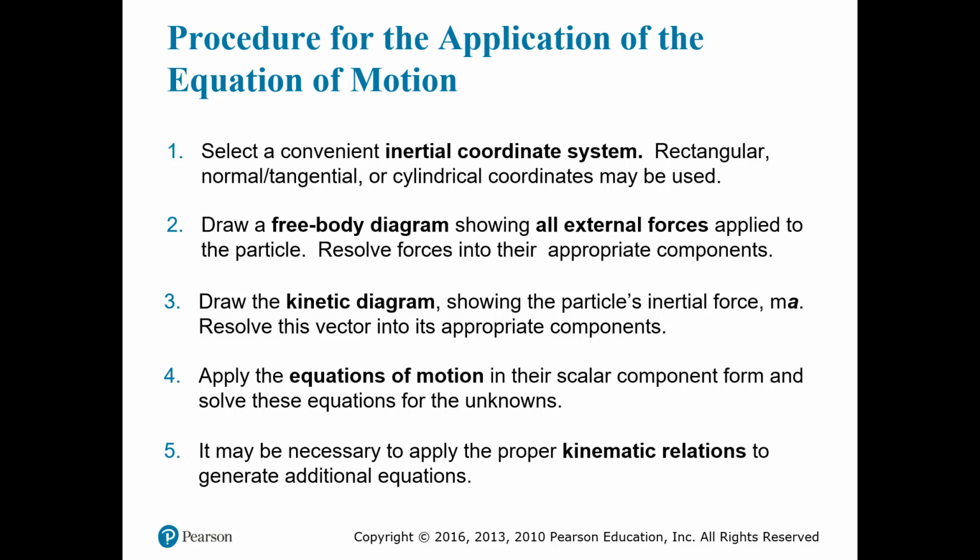Then once you have that established in your head, you have to draw a free body diagram showing all of the external forces applied to the particle. All right? You have to resolve the forces into their appropriate components. So once you have your x and y, if you have a force that is not aligned with the x and y that you determine, then you will have to resolve the forces into those components.